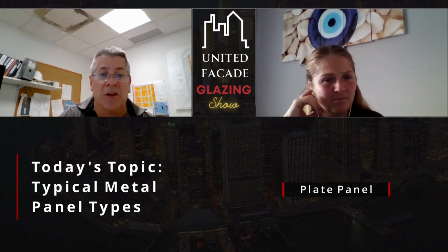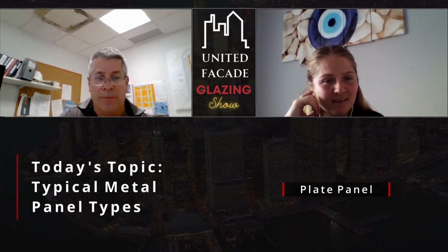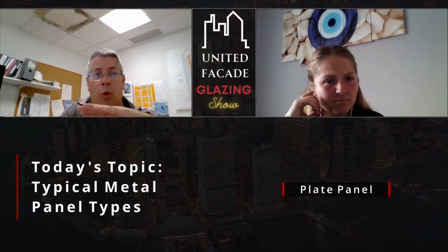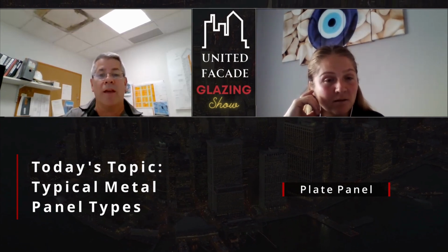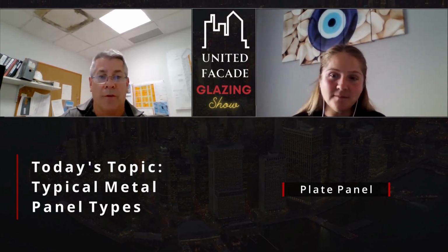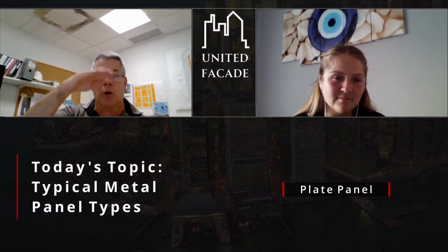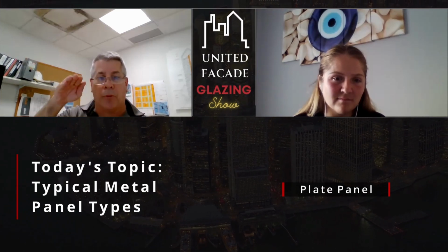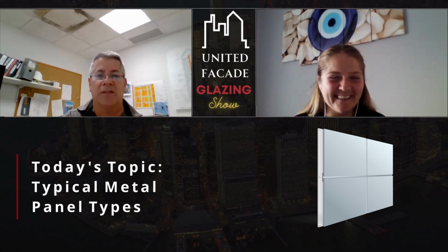Aluminum is a flexible material, and when I say it's a thin layer with a core inside it, that core gives you structure. If you had a thin piece of aluminum by itself, in large sheets it's going to want to do what's known in the industry as oil canning. You might get some ripples where it looks like it's not flat, it's not true.